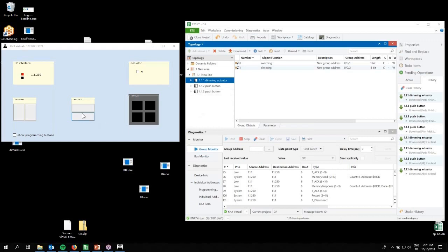Anyway, so I programmed the activator now. So let's find out if there is a reaction. I think this is also clear on your screen, we can see indeed a dimming effect here. So dimming up, dimming down, because of long pushes, but you can also follow in the monitor: switch off, switch on, dim up, off, on, etc. So you have seen it's actually quite simple. We just need to make two links, and this is actually the minimal configuration for a dimmer.